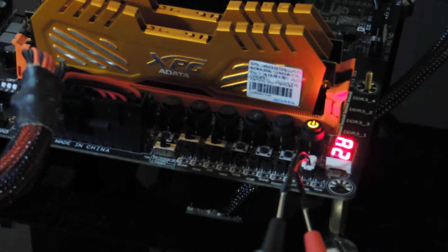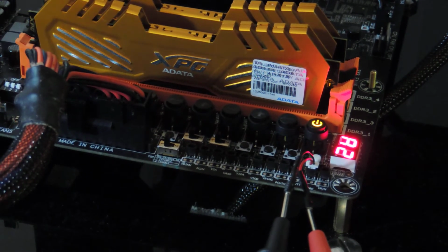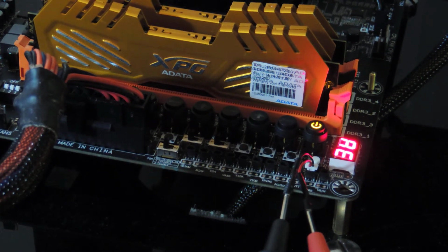And now the system will boot. You can see the vCore is going to push up to 1.283 volts. And now let's take a look at some of the system stuff going on here. So I have the voltage read points in there, so I can read real voltage because CPU-Z is lying nowadays. It just shows a VID.